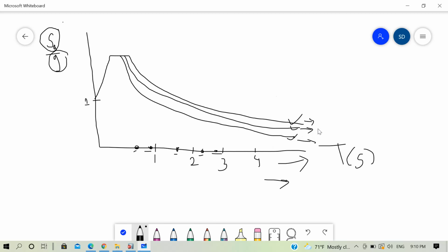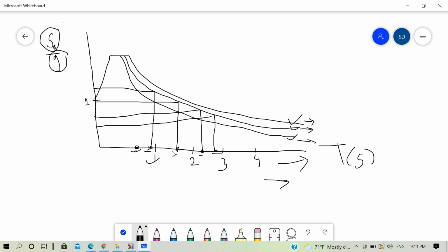We have considered that ours is a type 2 or medium soil. So from these points of natural time period, just draw vertical lines to the curve, and then from these points, draw a horizontal line here. Remember, this is just a conceptual framework, and this may not represent the actual time periods. I'm just giving this as an example. So corresponding to these different modes of vibration, we got different time periods, and for these corresponding time periods, we got different values of spectral acceleration. And these accelerations are now the loads that are applied to our structure.